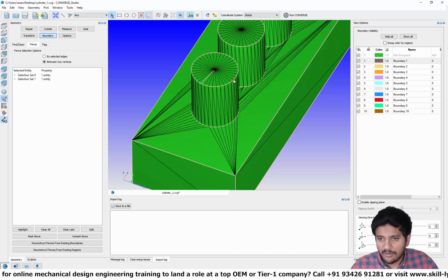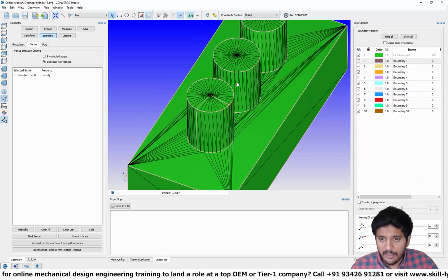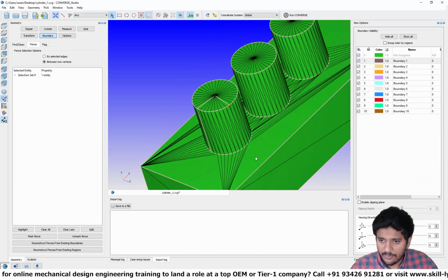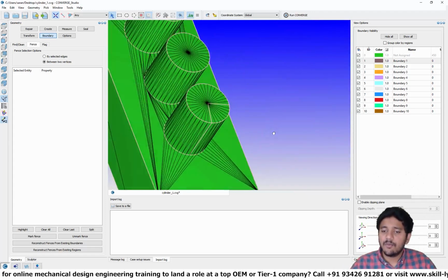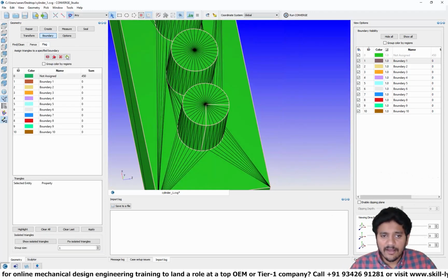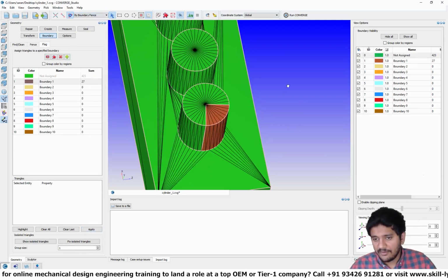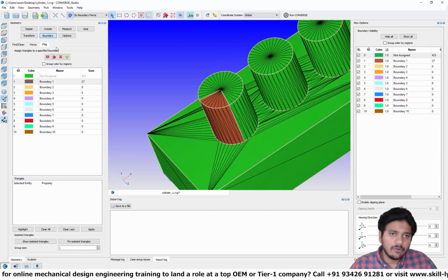Again, I'm just eyeballing a quarter of a circle, so it's really not accurate, but this exercise actually helps you pick the vertices correctly, rotate the geometry and manipulate the selection. All right, so you can see that I've created one boundary fence here. So if I go to flag and if I go to boundary fence, I should be able to select this guy and this guy separately, add that as a single boundary. All right. So now would be a good time to talk about rotational transformations.